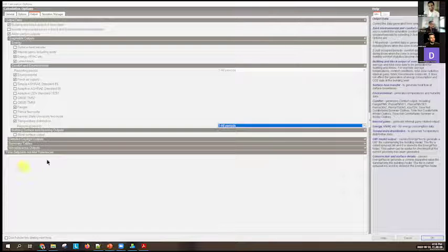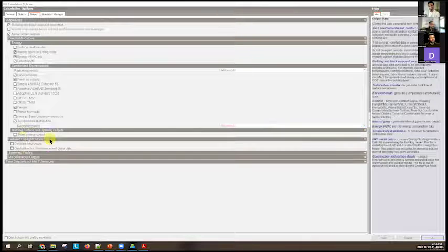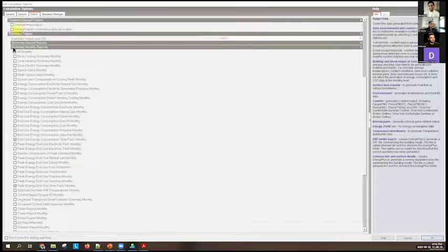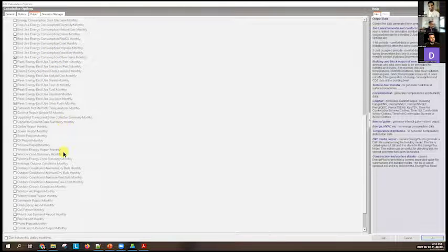Okay. And I'm not going to ask it to store any outputs at this point, none of the other bits. But in the summary reports, I might ask for zone cooling summary, zone heating summary. And if there were others that I was interested in, I could have. But none of the mechanical system reports are useful at this stage because we haven't defined the mechanical system yet. We're using a simple ideal system.